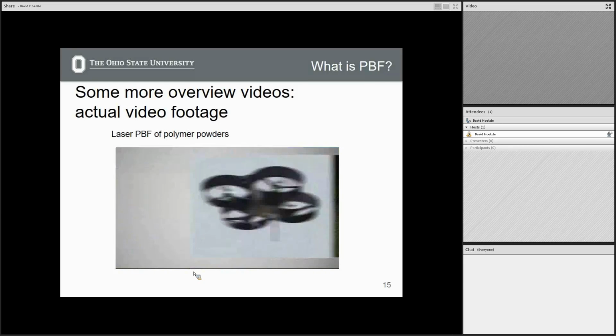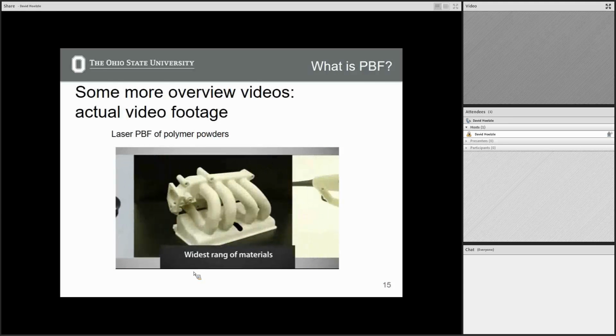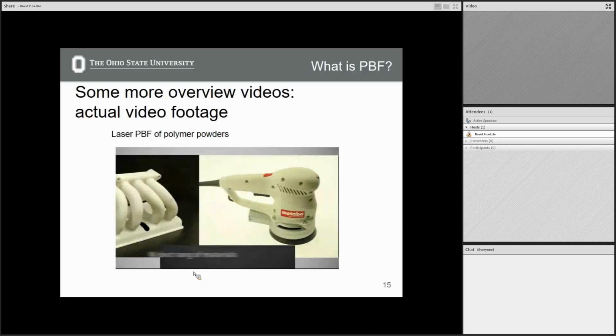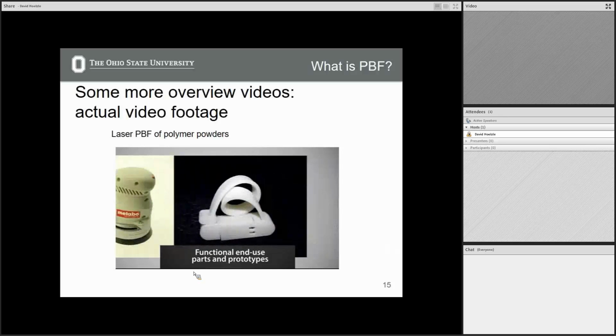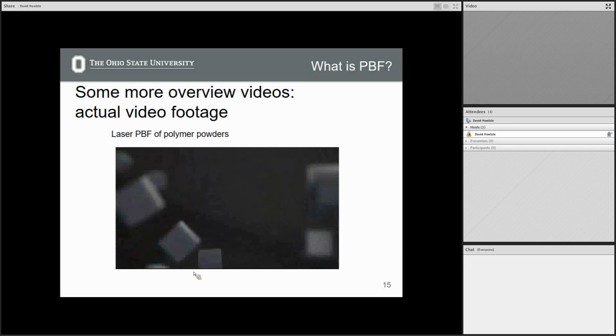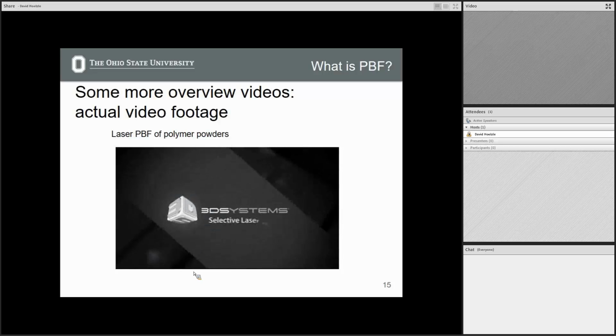The other thing, because the temperature gradients are so small, you can make some pretty large parts in the polymer processes because you don't have to worry about thermal stress generating from large temperature gradients. You saw the part he was holding was like this big. That's very difficult to do in the metals processes, to get a part that big.